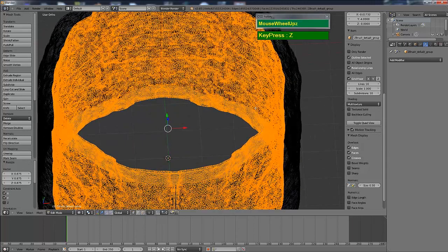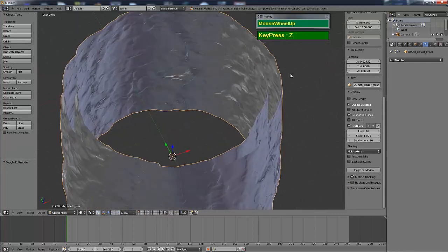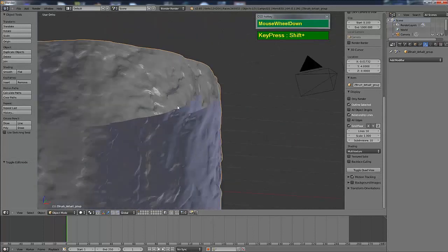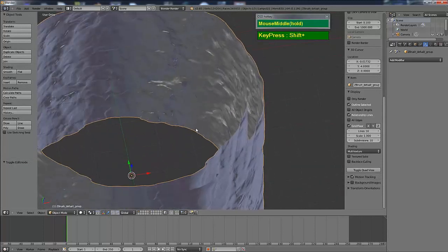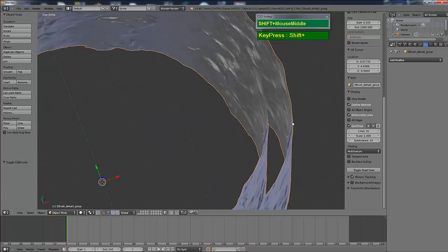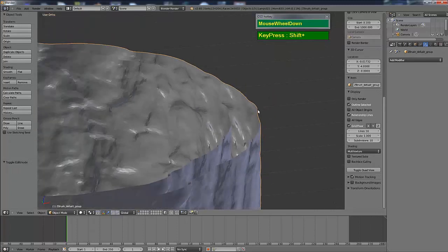Let me show you this in shaded mode so you can see the internal and the external shell. Both of these are identical, with the same number of meshes and faces. I want to join the edges and cap them, and you can use a command called bridging.